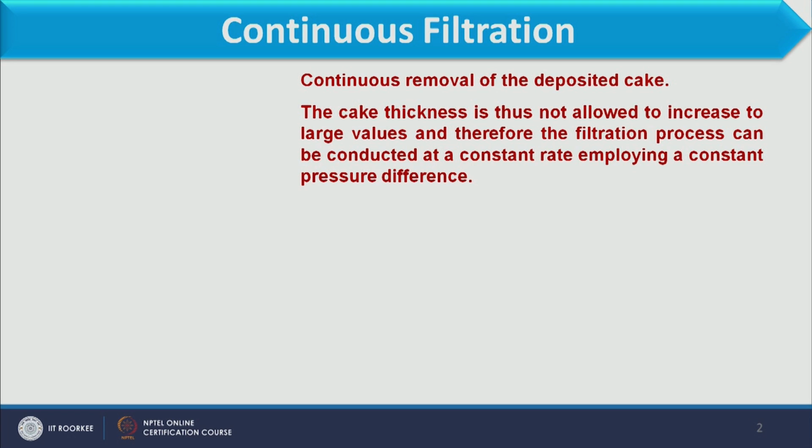Now, why do we increase the pressure? Because after some time when the filtration is carried out, the cake is formed over the filter media, and it offers resistance in the path of the liquid to move, and therefore we have to increase the pressure. Once we operate the system, after some time cake is formed over the filter media.